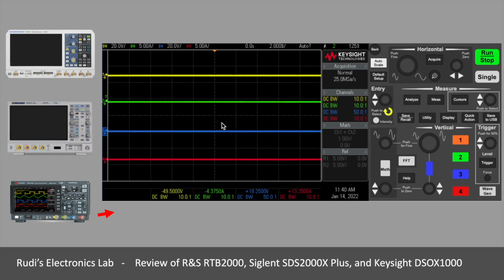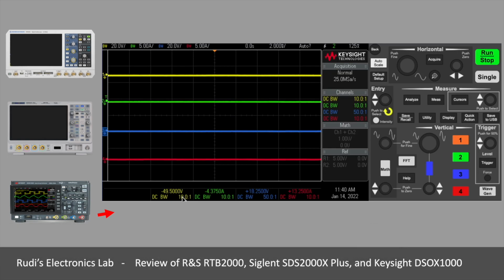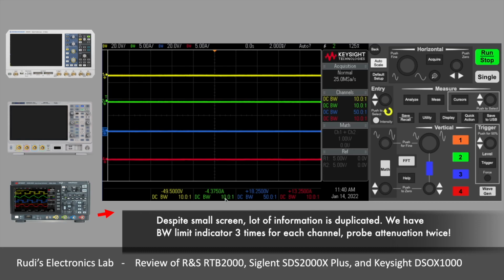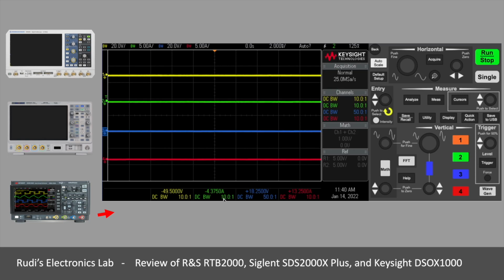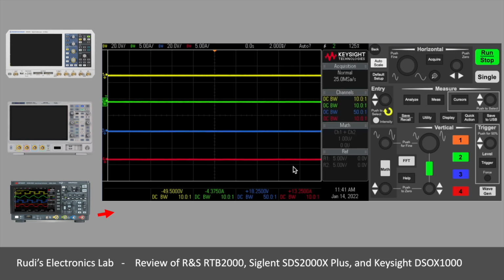We're going to see the same channels here in a moment, so I prepared the same settings for the probes. What we see here is our voltage probe 1 to 10. We see our current probe here. It's shown a bit different, but it's actually 100 millivolts per ampere. Actually, let me go to that probe and see what value is in there. Yeah, here we're nicely seeing 100 millivolts per ampere, but still here it's showing itself as 10 to 1, which is not wrong, but less convenient, I would say.